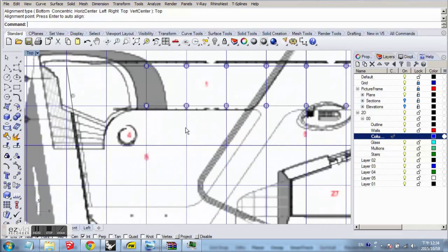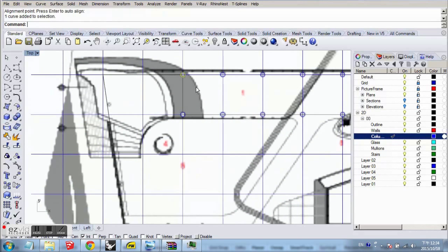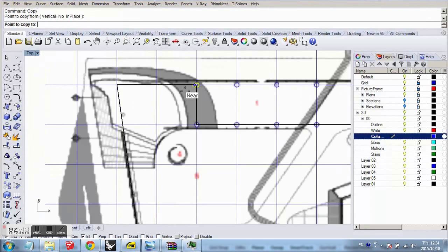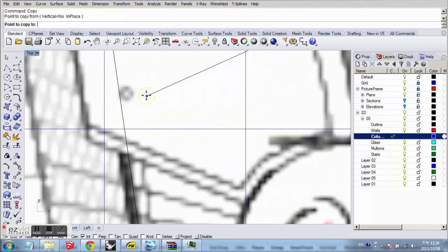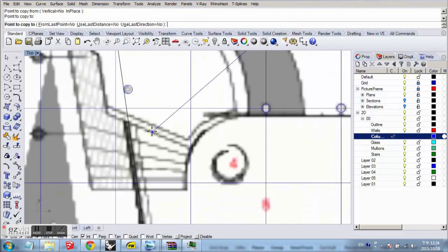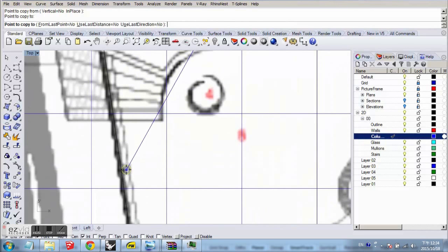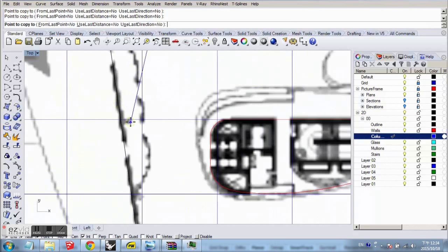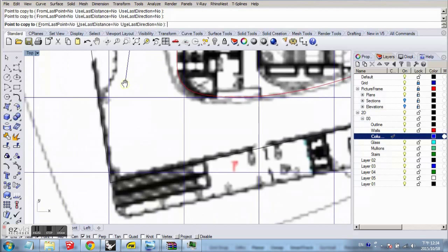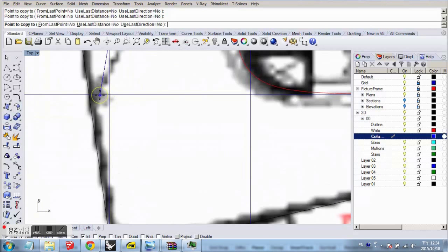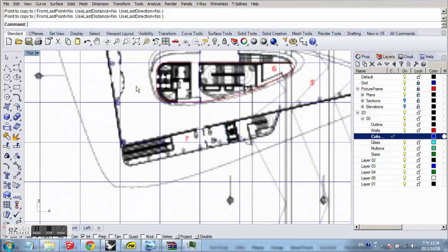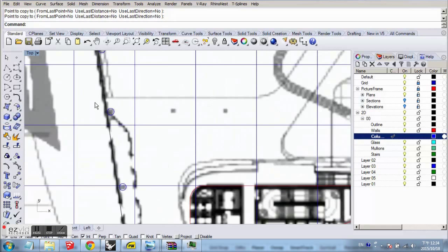Alright, there's a row of columns in front of the entrance facade. Let's select one of the columns and choose the base point for copying in the center. Okay, so now let's copy them along the facade using the picture frame as a reference. Just those two columns missing. Let's select the column next to them and hold Shift to copy them nicely orthogonal.